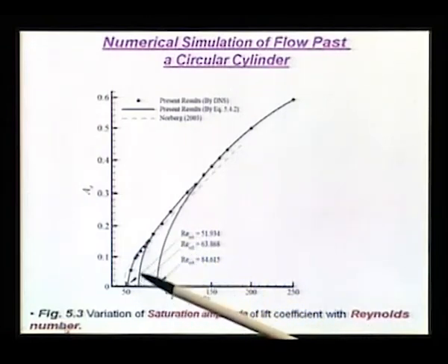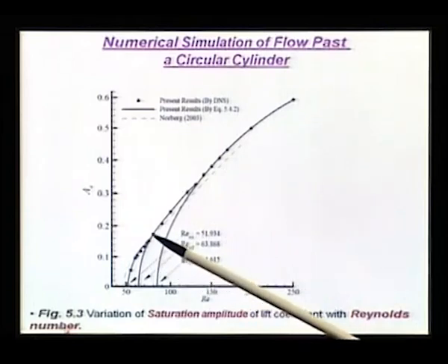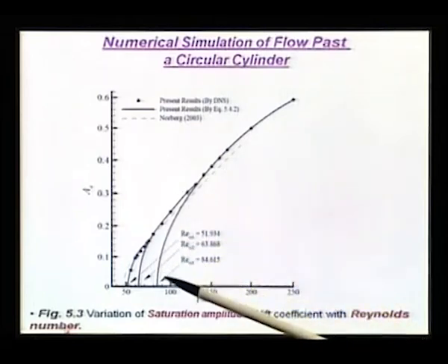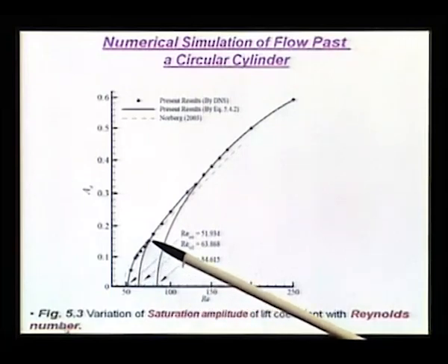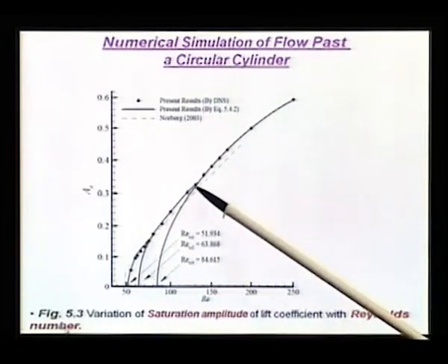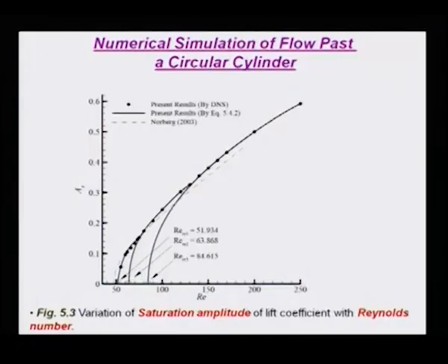Well, how do you know there are three parts? You see those kinks. We are noticing there are two such kinks. So, we are saying that this could be the first bifurcation meeting the second bifurcation somewhere here, and this is the meeting point of the second and third bifurcation. So, this is an example where you can see it is very much inbuilt in your governing equation, Navier-Stokes equation.